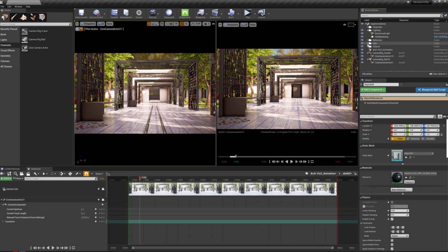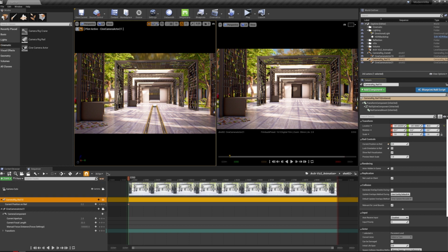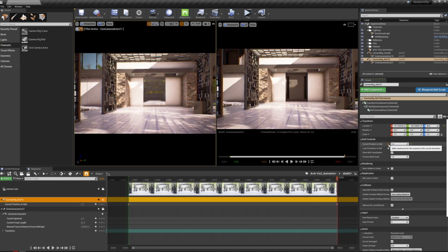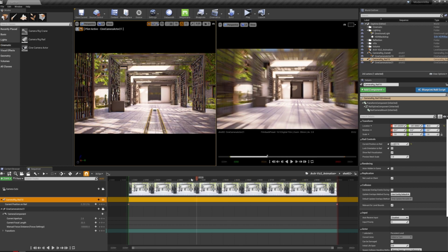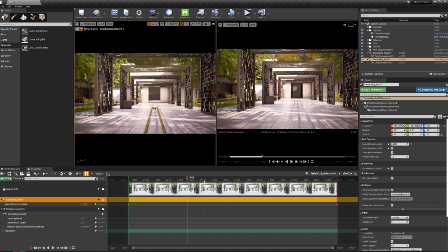Sorry about that. So the camera rig rail, we're going to move it from 350. Make sure you go back to the beginning of your shot frame and click on the position of the rail at 0, and let's move it till the end, which is 900, and make this 1, and click another keyframe. So if we move the time frame here, you can see that now we have a movement for the camera on the rail as it has been set up.